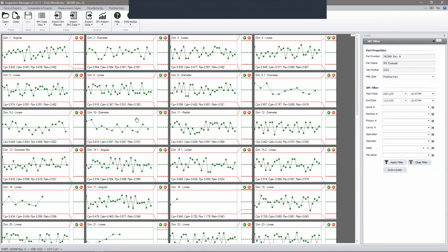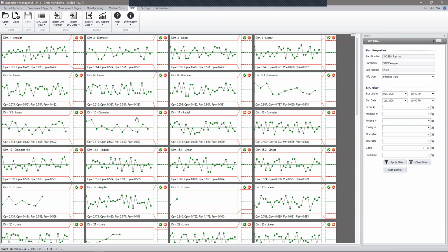All right, so that's on the back office side of being able to see the SPC trends, but what about on the shop floor where we want to see things in real time to be able to adjust our processes before something happens? We can be preventative with our quality inspections, not just reactive, right? And so if I'm seeing a particular trend away from nominal in a consistent direction, then I want to correct my process, adjust my offset, see what else is going on the CNC machine, something like that.